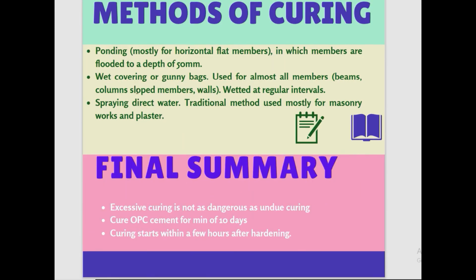So finally, we have the final summary. It says that excessive curing is not as dangerous as undercuring. All right. So curing is very important for concrete members and for structural members. Even if it's excessively cured, it's fine, but it shouldn't be undercured. The curing shouldn't be less. That's dangerous, and it affects the strength gain of the structural members.